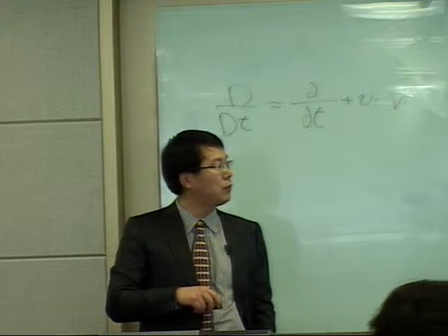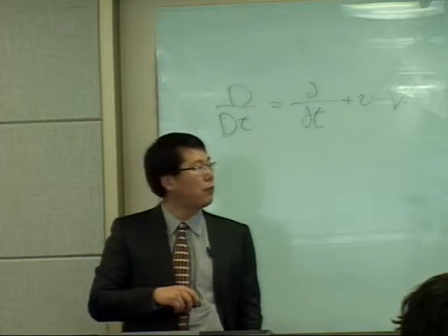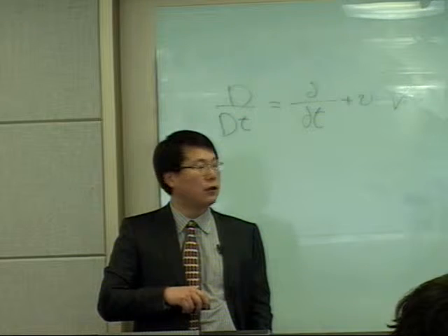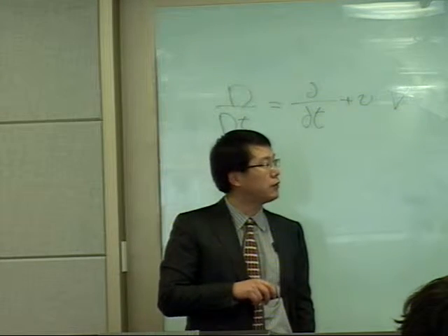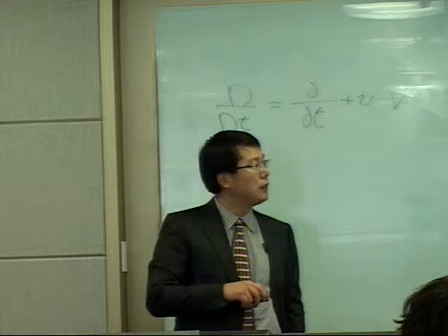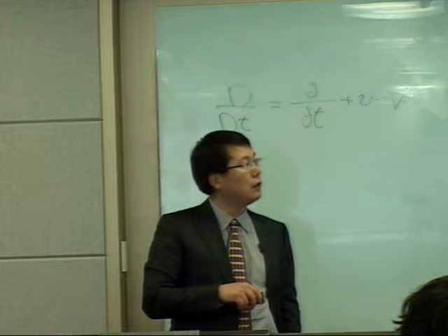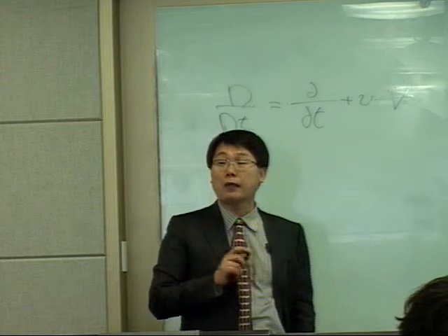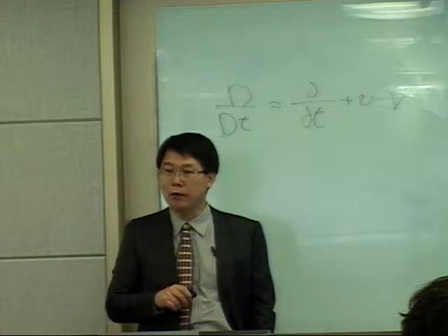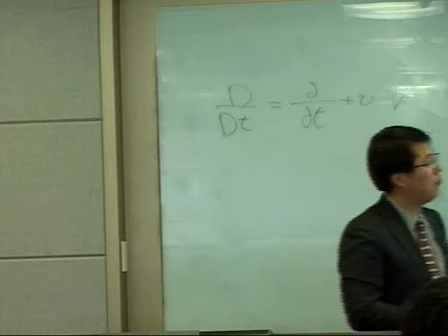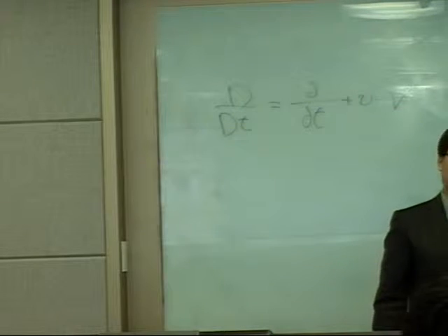In this example, we have the temperature profile in terms of position. We have a gradient here, dT/dx at x1. Since the slope is positive, the heat flow is negative, and the heat flows from this to this.